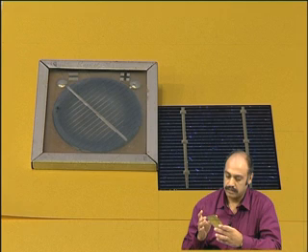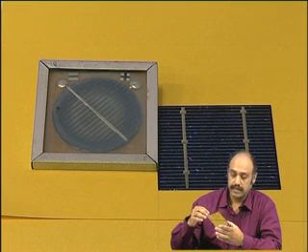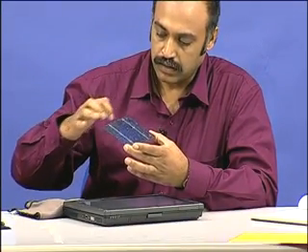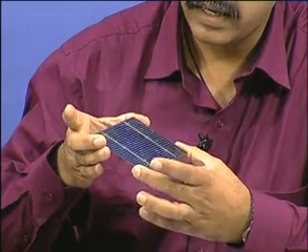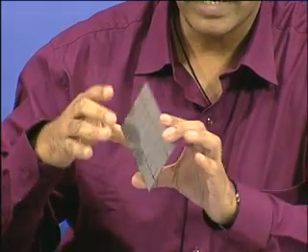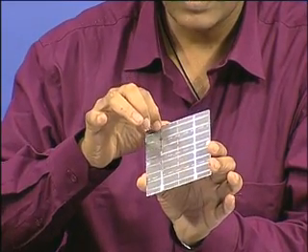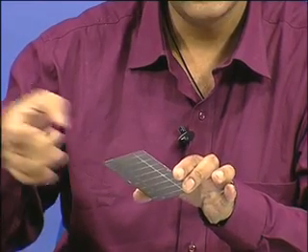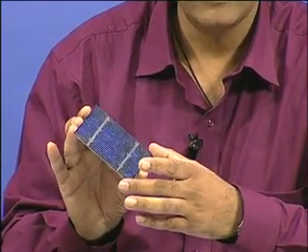You see, this is actually a p-n junction. The top layer would be an n-type layer, and the sun rays will fall on this, and on this there are metallizations which are soldered on one layer, and on the back side also you will see the metallization, so that we can solder one lead on this and one lead on this side and take it off, and those would be the two terminals of the photovoltaic cell.